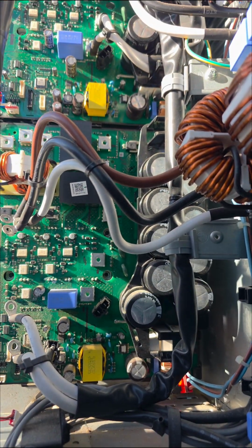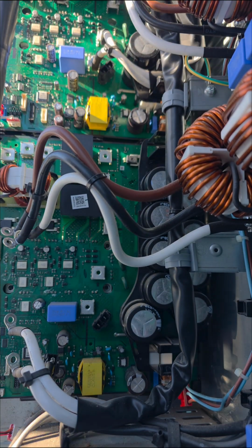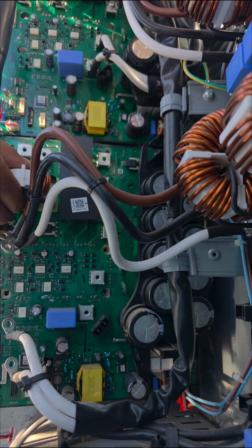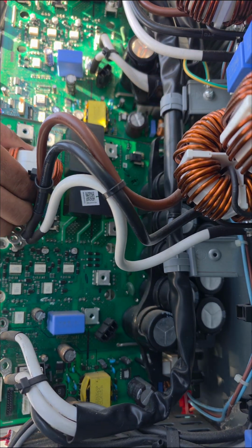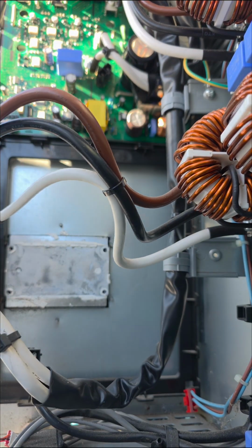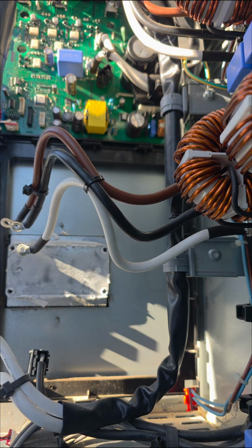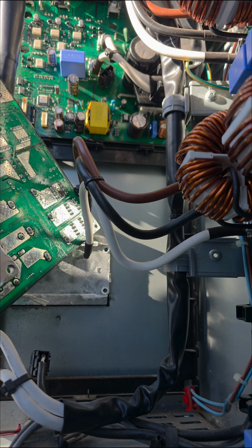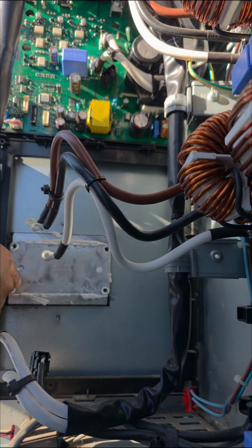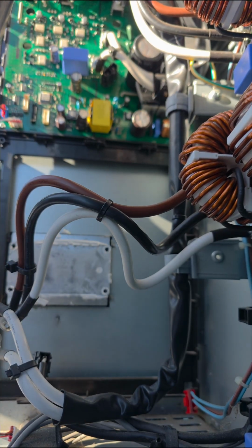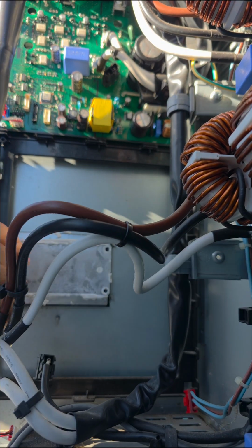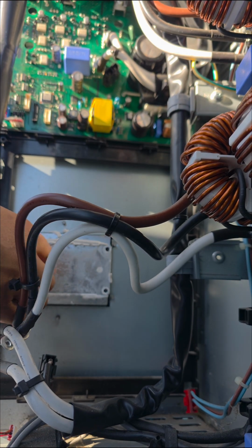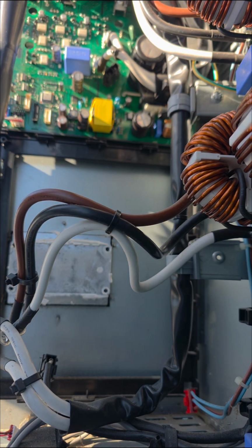The system will protect itself and give a fault code, because that IPM can get upwards of 100 degrees Celsius, especially if you don't have any paste, or what we refer to as a bad print. So you can see most of the paste is just all smudged and pushed to the sides, and there isn't really a lot of contact over here. That's heat transfer paste.